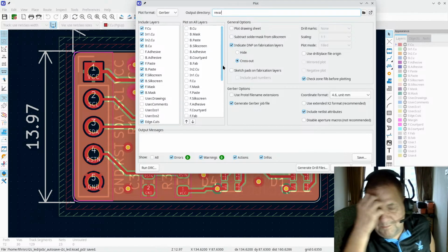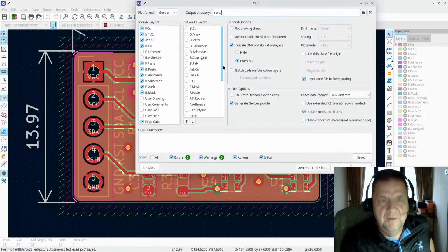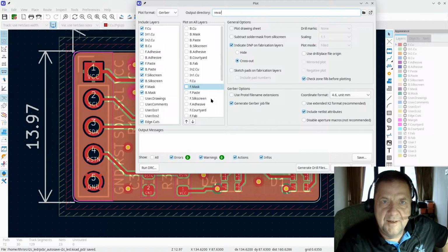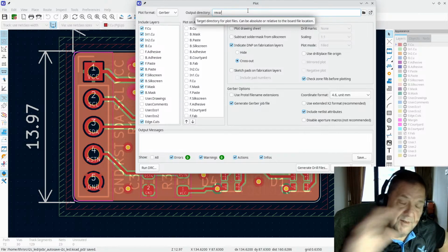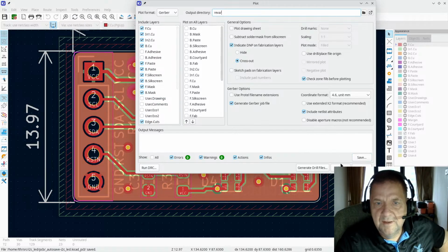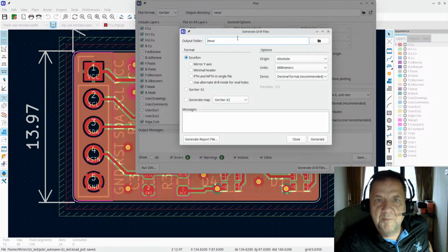It's this project, I should say, I deliberately kept it simple and stupid. I mean, this is about as simple as it gets, and that is deliberate. Anyway, back to this. I need to create my Gerber files, and essentially Gerber is a standardized format that all these PCB manufacturers use, and you basically create a Gerber file for each layer, so it's a bunch of layer files. You also have a drill file in here, and we need to do that separately. I put it in there as well.